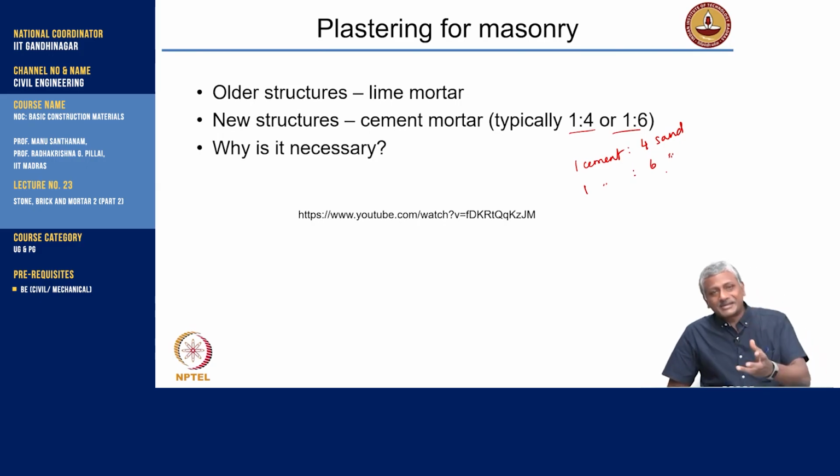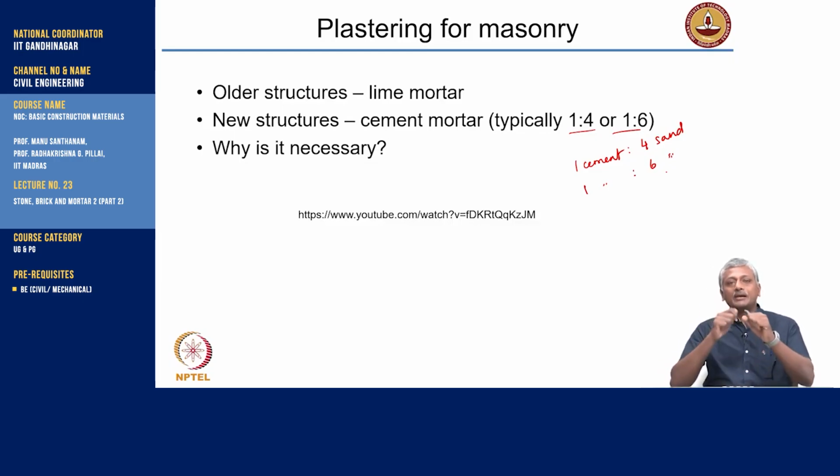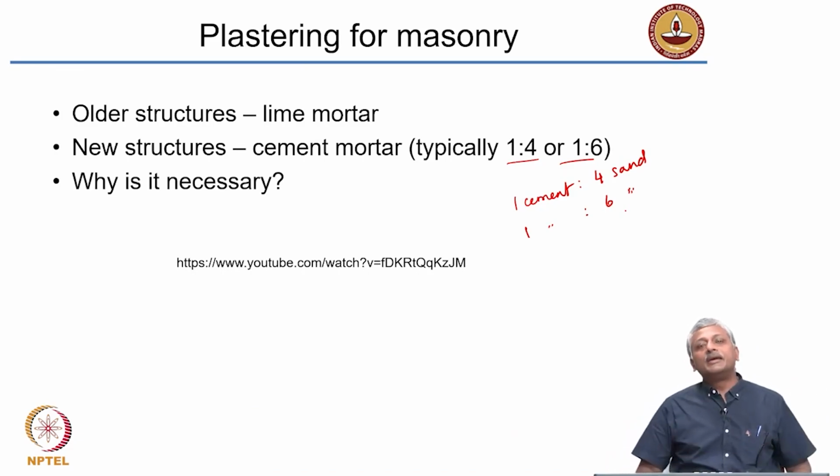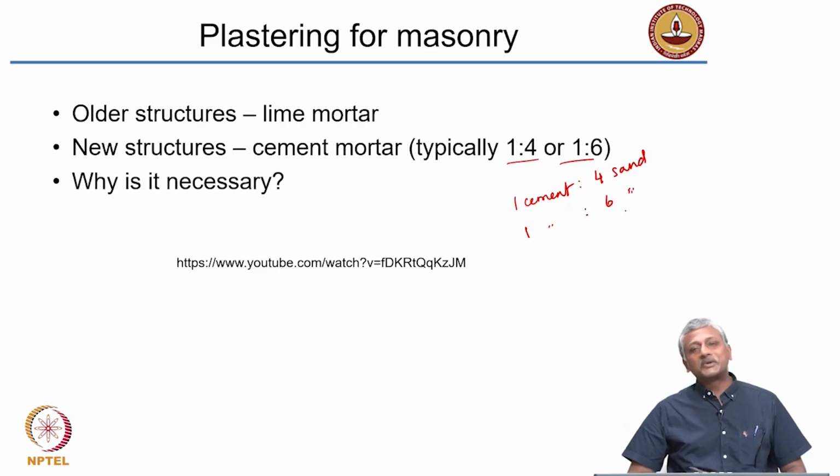However, interestingly, in our country, strength of the plaster also seems to be given a lot of importance. Why? Because you want to put a nail into the wall. If the process of putting the nail, drilling and all, completely fails off or chips off the plaster, it's not something that you want. So, some level of strength is required to handle the process of drilling, nails and so on. But sometimes people do very random tests, like take a hammer and start striking the surface of the plaster. It's not a good idea to do that, because plaster is not supposed to be a very strong layer. Because of all this, people have started making plasters as very strong mortars, and that's not a good idea. You have to make a plaster as a weak mortar.